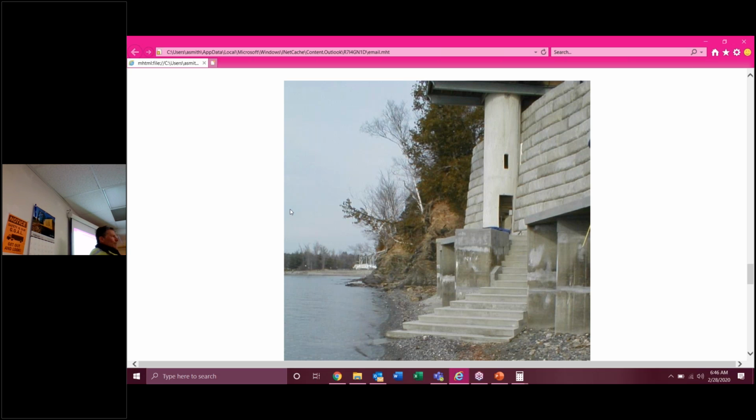And actually, these were an older version too. I don't know if we installed these. They were way back. These are actually precast square pipe pieces standing on end. And then there was a deck board on here. And then when this work, the stairs and the wall, was done, this was existing. The riser was existing. They had a problem, you can see some of the shaly type rock here along that face on Shelburne Point. It breaks down really quickly with weathering. And of course, there's groundwater that's continually seeping out onto the face, and the freeze-thaw just turns that to mush. So that whole face was to protect that.